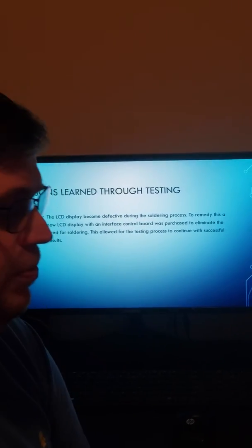Some of the lessons learned during this were ensuring you have a clean soldering tip and using proper soldering techniques. I damaged my original display and had to rush order a secondary display, this time using an integrated chip. This will help reduce errors in the future and make it easier to mass produce this system if needed. Also, it allowed more I/O points to be used on the Arduino for future use.